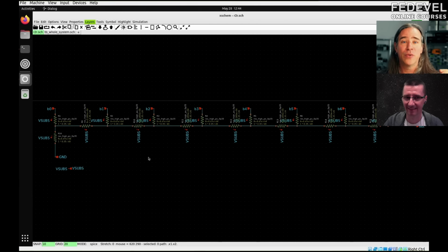Maybe all the resistors will be 20% greater, but it doesn't matter because 2 times that and 1 times that just comes out fine. You just need to use the same resistor everywhere, and it doesn't matter if it's not exactly the value you wanted, because they are all relatively the same.